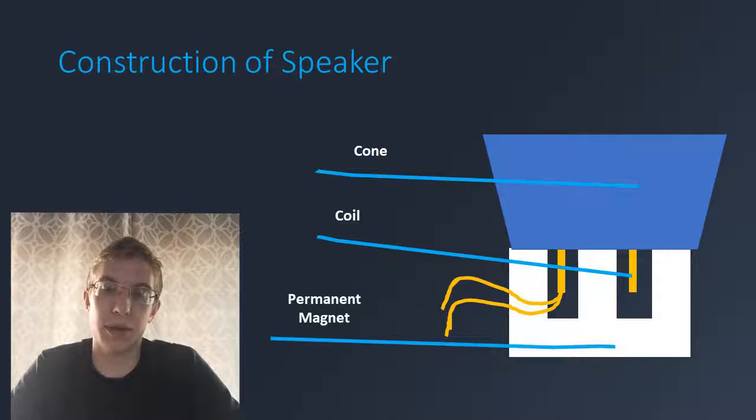With respect to the coil itself, increasing the current or increasing the number of turns is going to boost the intensity. The other important factor is the material of both the coil and the magnet. The permanent magnet will need to be something like neodymium, a hard magnetic material, and the coil should be a soft magnetic material in order to minimize hysteresis losses.